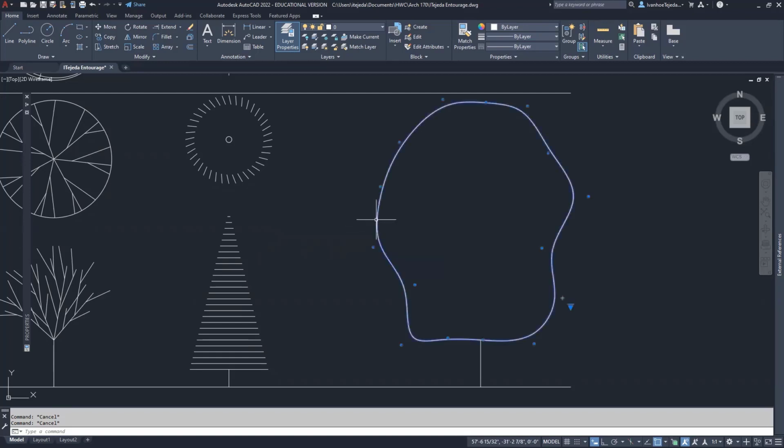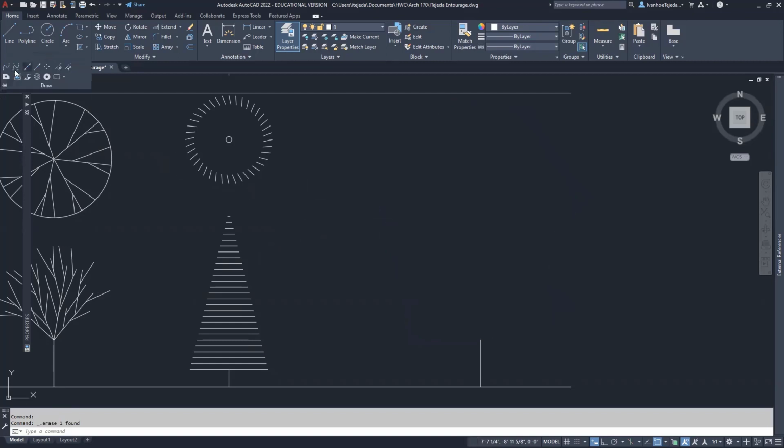So let me go ahead and select this and delete. I'll go back to my draw drop down. And I believe I did a spline fit, and now I'm going to do spline control vertices. I'm pretty sure it's the same thing, but instead of beginning one way and then switching it over, I will now start with, let's see, a first point here. And as I pick my next point, you see how now it is allowing me to use those control vertices.